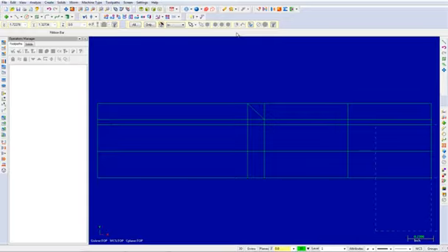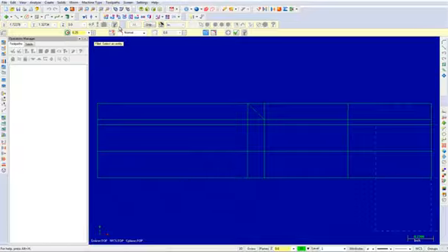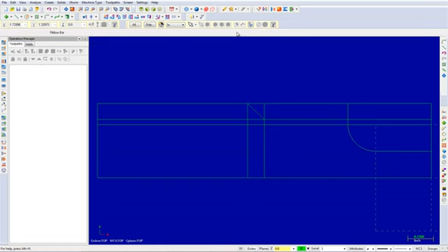From here, we will create a fillet. In this step, we will use the Create Fillet command to simultaneously create a fillet and trim two entities. Select the Create Fillet Entities command. Input a radius value of 0.25 and make sure that the rest of the buttons in the ribbon bar appear as shown. Select Entity A and Entity B as shown and then pick the OK button to exit the command. Your part will appear as shown.